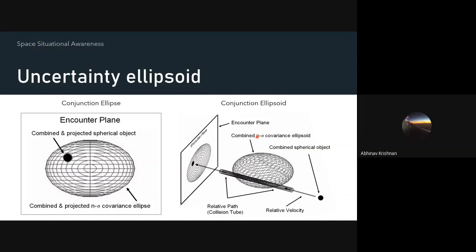As you go high in the orbit, beyond 2000, 3000, even 10,000 or 20,000, you would realize that the relative velocity stops at 4 kilometers per second. If you go to GEO, it could even be a few meters per second. That's how slow the encounters happen. So they spend a lot of time comfortably within that ellipse. So the concept of uncertainty drops significantly when you go to geostationary or geosynchronous orbit.